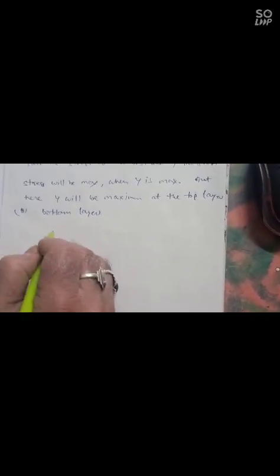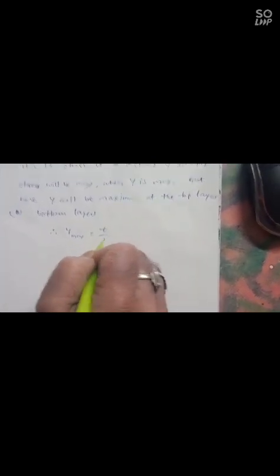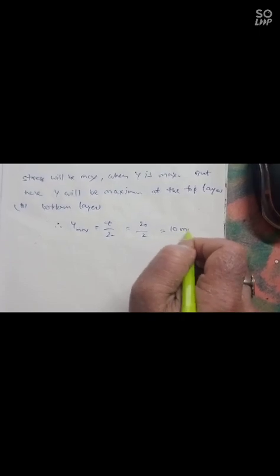It will be maximum at top layer or bottom layer. So y maximum is equal to T by 2, which is 20 by 2, it is 10 mm.